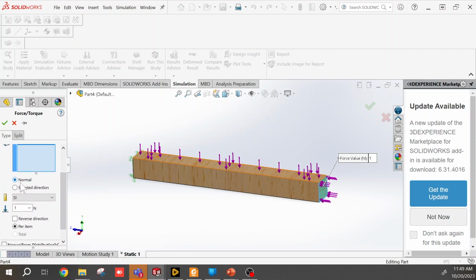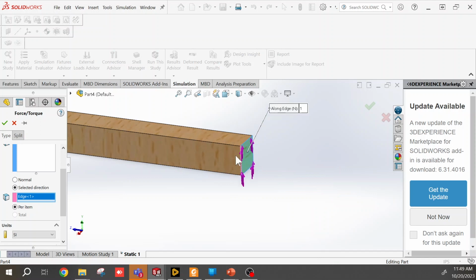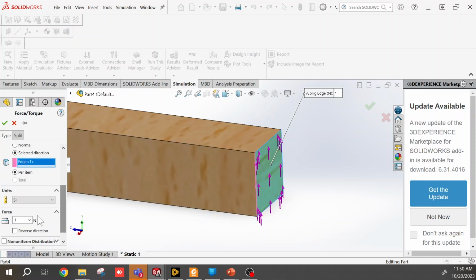We don't want the direction to be normal to the surface. We want it to be in a direction that we're specifying. So I'm just going to say that it needs to be in this direction here. I click an edge as a geometric feature that I can use to define the direction. And you can also reverse the direction to make it down.